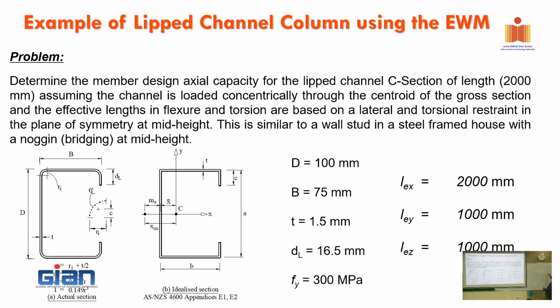Okay, you see my drawing? So it means that this is the same cross section, but because of twisting, this end will go up, that one going down, that one going down because of the twisting. Okay? And those displacements, we call warping displacement.